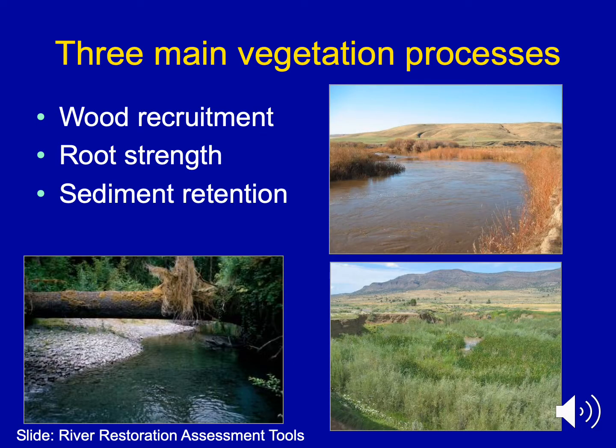Of those boundary processes, calling out specifically vegetation, I think it's, in general, very underappreciated in its impact on channel morphology. Vegetation generally does three things. Through wood recruitment, it provides a habitat forcing or morphologic forcing mechanism. It is also a sediment storage and scour mechanism. In some systems you have a lot of gravel trapped behind it. But in finer grain systems, this really changes where your deposition happens and your residence time as sediment moves through our system.